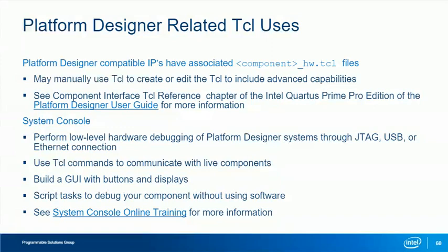System Console is our low-level hardware debug tool used to interact with the Platform Designer components through a USB, JTAG, or Ethernet connection. The entire tool is Tcl-based, so you can easily script communication with components, as well as easily build custom GUIs to display results. If you're interested in this, please see our System Console online training for more information.